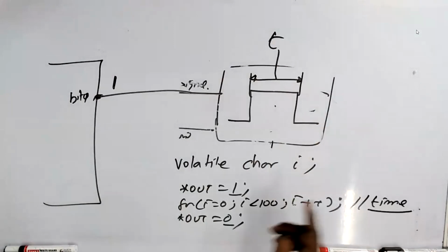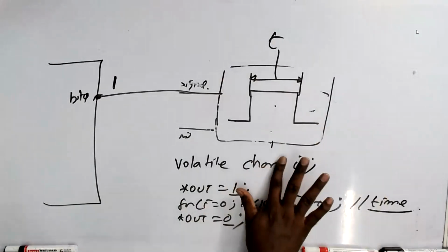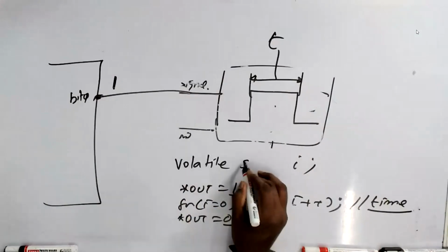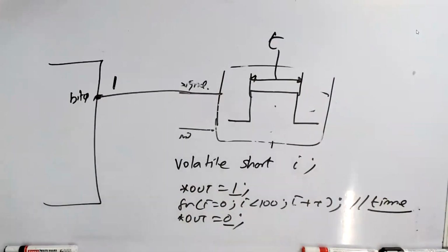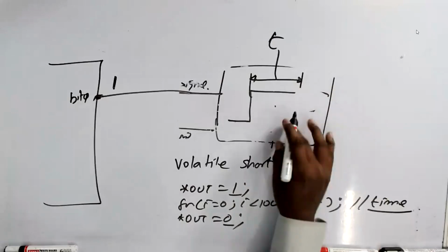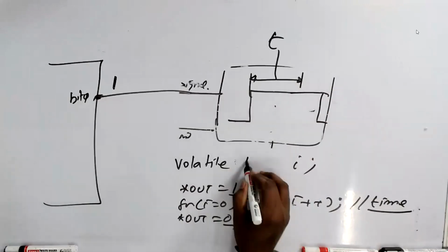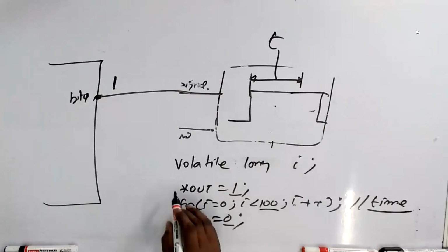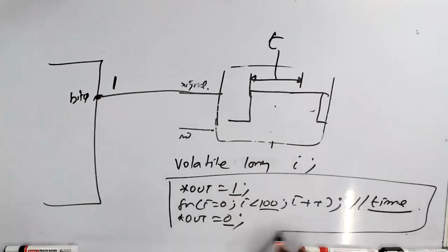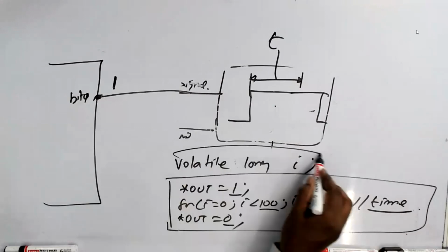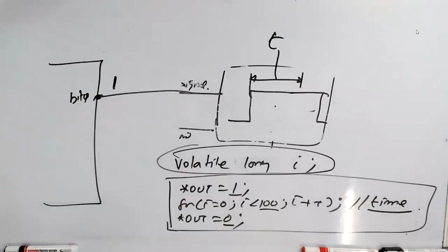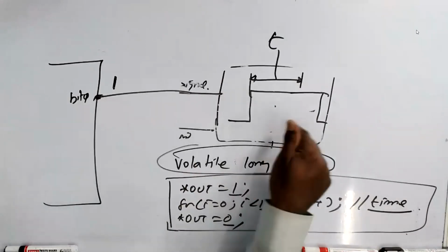Now you know how much time this loop will take. But if you change the char to short, 16-bit, the time will increase. If you change it to long, you don't change the program, but you change the width, then this timing will change.